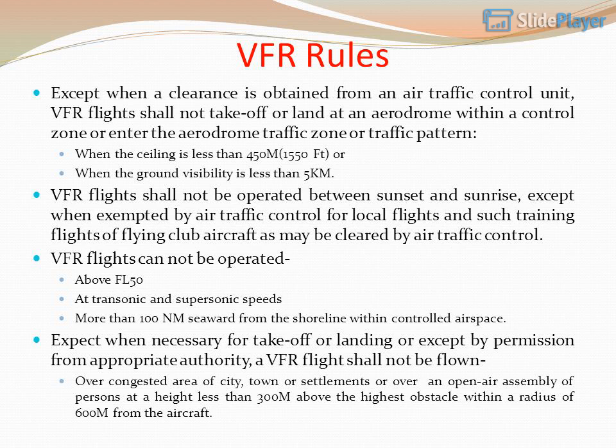VFR flights cannot be operated above FL50 at transonic and supersonic speeds, more than 100 nautical miles seaward from the shoreline within controlled airspace. Except when necessary for takeoff or landing or except by permission from appropriate authority, a VFR flight shall not be flown over congested areas of a city, town or settlements or over an open-air assembly of persons at a height less than 300 m above the highest obstacle within a radius of 600 m from the aircraft.